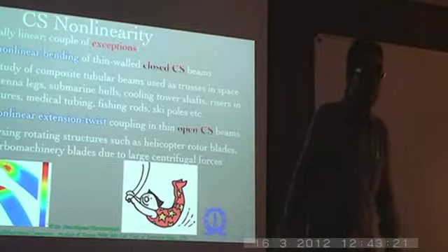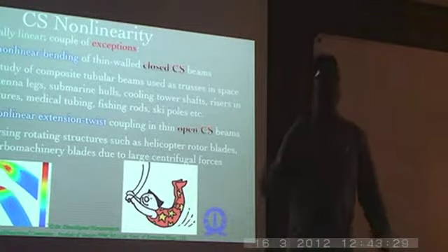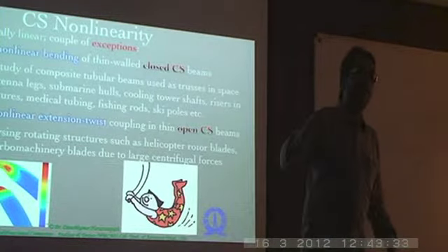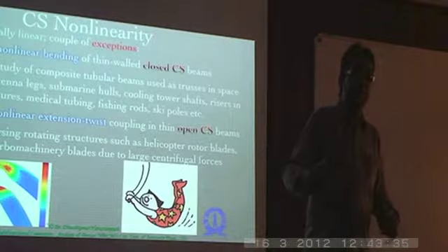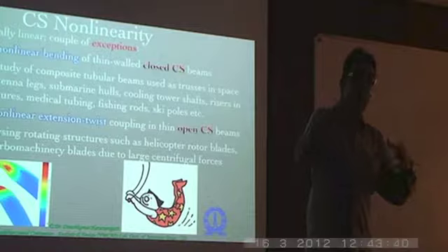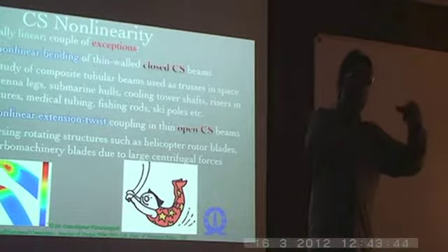But in the sense that at a cross-section where you apply the load, you expect that cross-section to distort a bit much more than the others. See, typically the way the aircraft wing is designed is such that where you have concentrated loads, you will typically have a transverse stiffener, a rib. In the case of the fuselage, you'll have bulkheads. So for example, where the wing is attached to the aircraft fuselage, you will have bulkheads there.